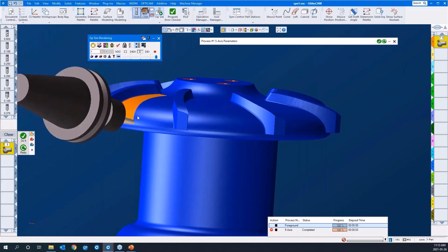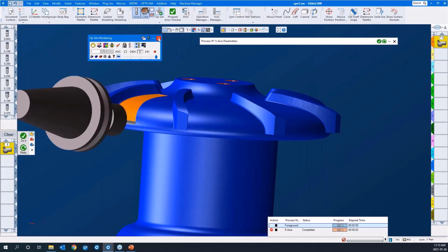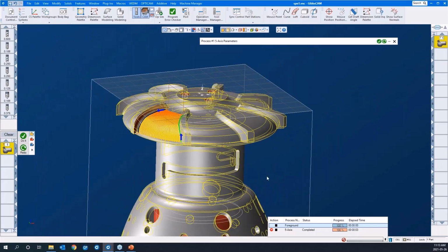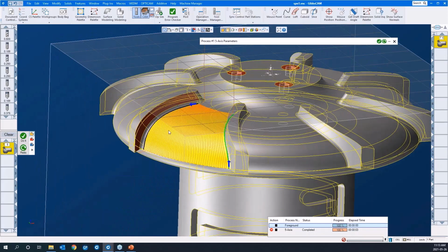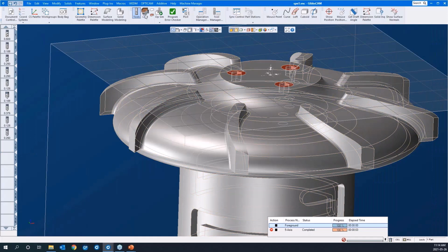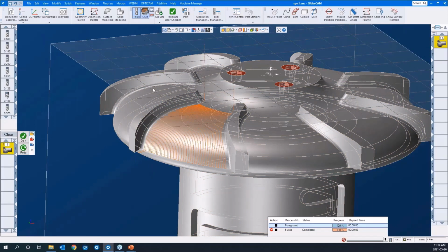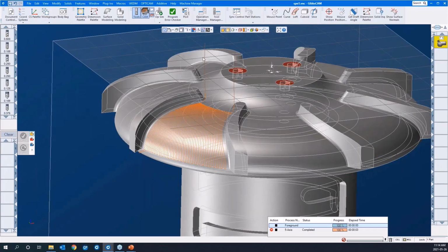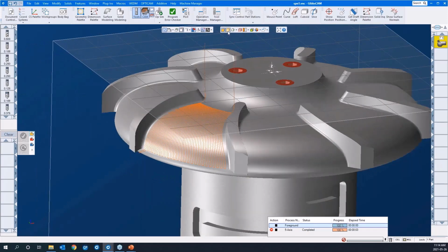Okay, so we're milling with the end of the tool here. So a lot of the 5-axis module is end milling, but there's a very important component to 5-axis, and that's side milling. Swarf milling they call it, side wall area relief feed. So let's do that. We will side mill one of the blades here.